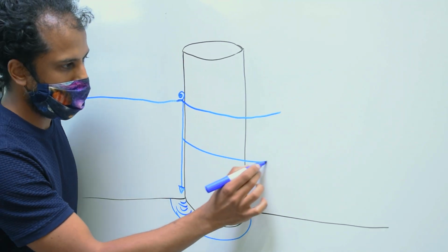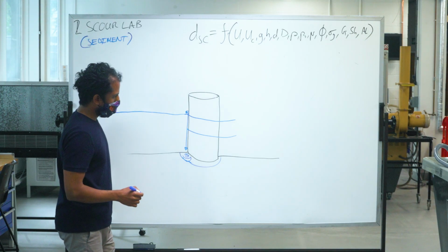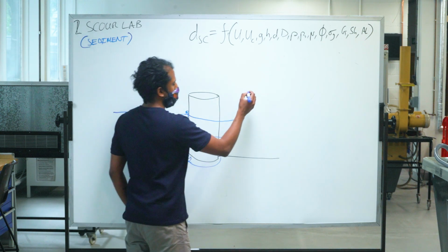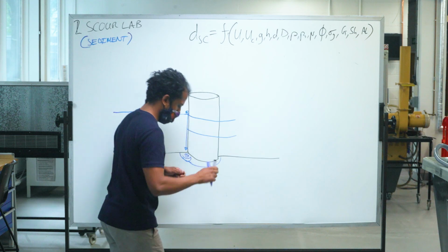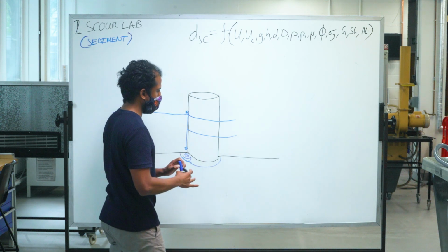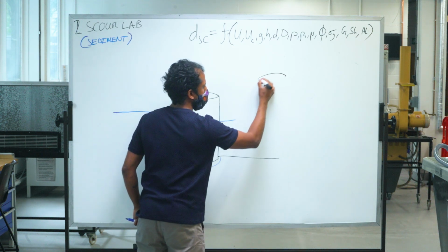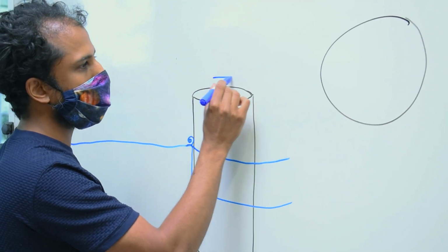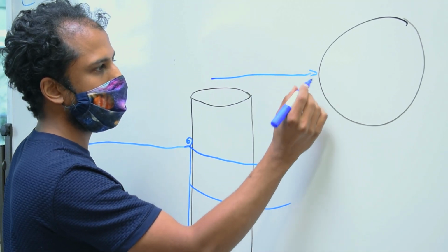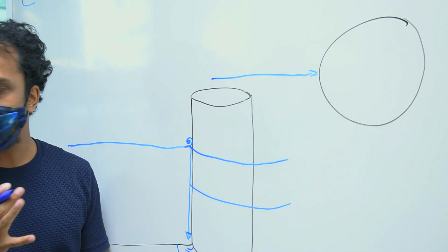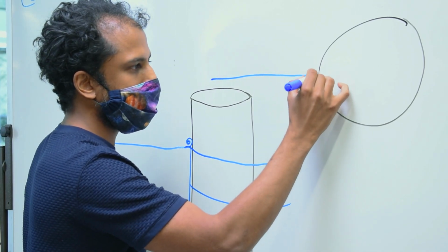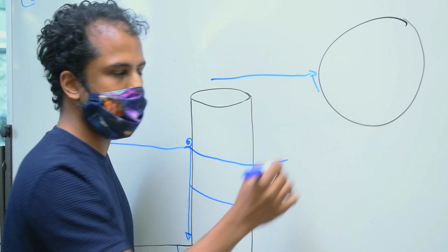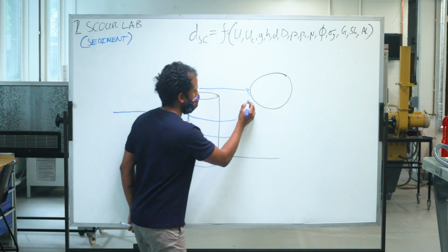And let's draw it like this. When we're thinking about what happens to the flow around a cylinder, let's have a look at the top down, and then we can focus on this. So if you recall, our flow approaches our cylinder. It reduces to zero velocity, maximum pressure, and then it's deflected around our cylinder, and so the velocity starts to increase. And with that, the pressure must decrease.